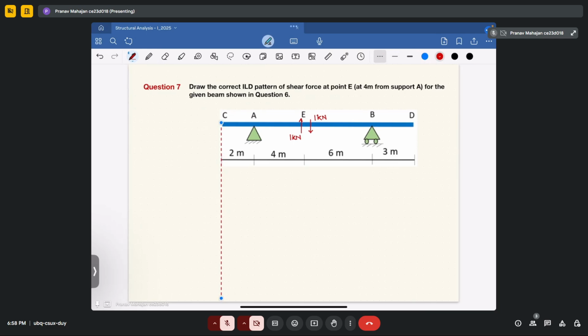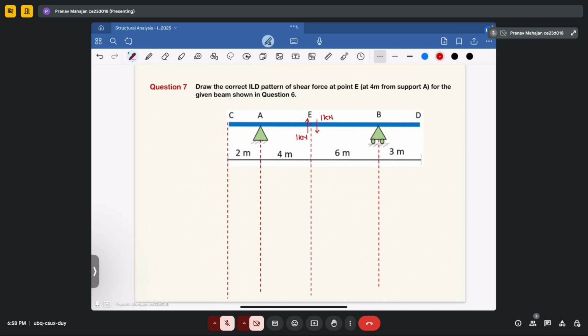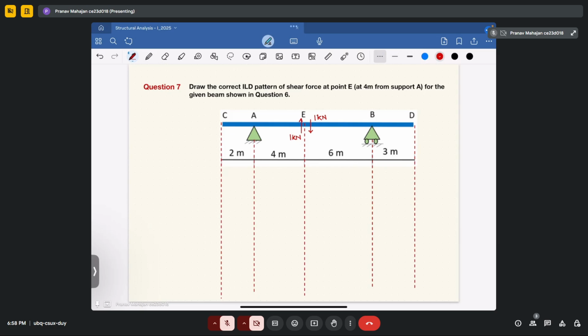As we have already seen, for the shear force, it is based upon the deflection profile of the beam. So if I say due to this unit load, it is applied at the 2 points of the beam, how the deflection profile will look like. So first draw that. If I am taking only this point load on the left hand side of the section, your deflection profile in the beam will look like this.